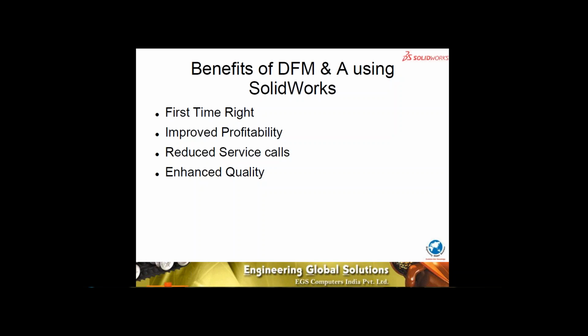So when you take the combination, you get 729 combinations of the product variants. Necessarily you will have to come up with an automation process. So as a part of the design for manufacturing and assembly considerations, they have developed a fixtureless assembly. For example, one of the components itself becomes the fixture. These kinds of unique methodologies that we can adopt as a part of our